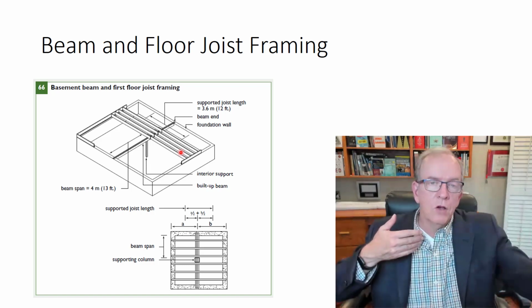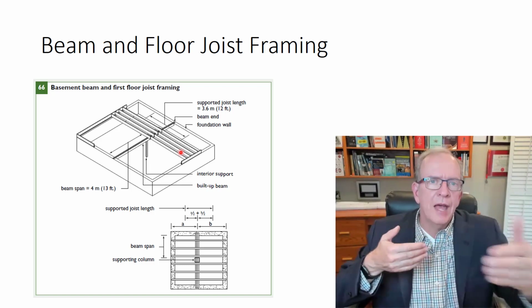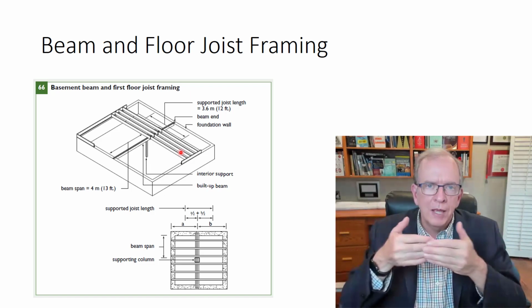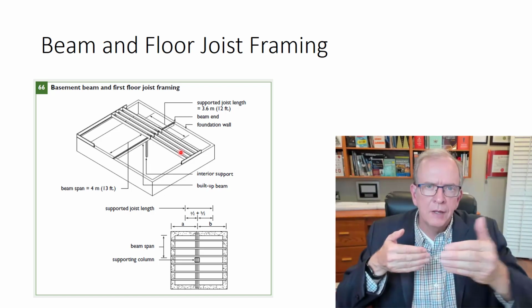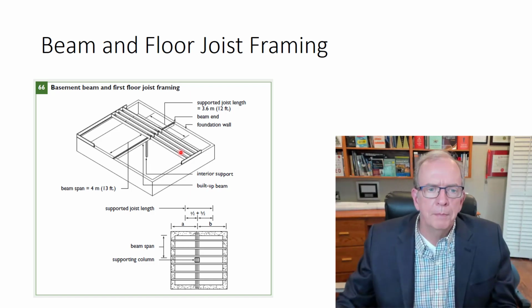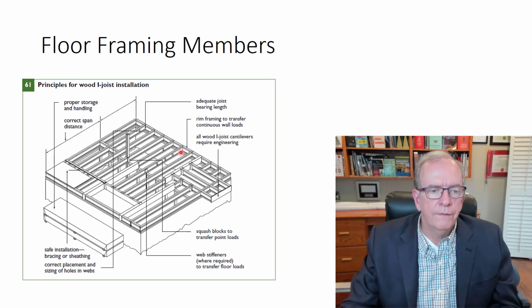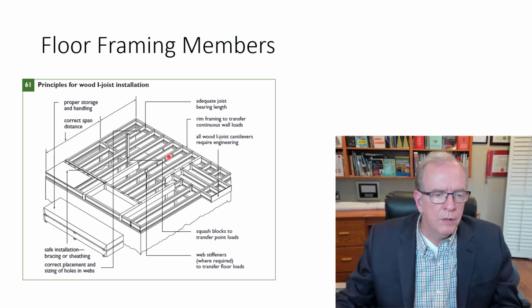If you're spanning a longer distance, so it's sort of at the end of that joist's ability to span that difference, they'll probably bring them closer together, and that might allow them to span a little bit further with those members because of the strength being spread out amongst the members. So you'll see that that's where the different spacing comes in.